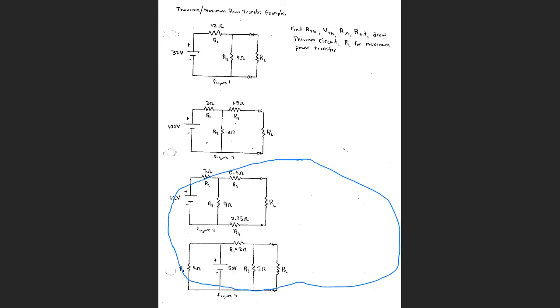All right? Well, let's Thevenize it. So when I Thevenize it, I remove the load. Mark the terminals. Set my power source to 0.